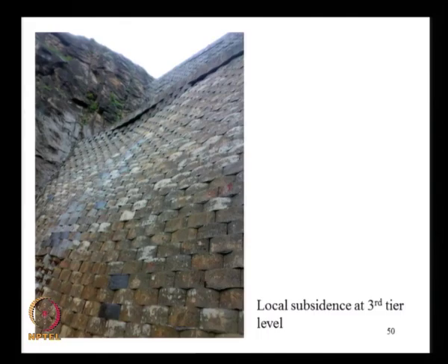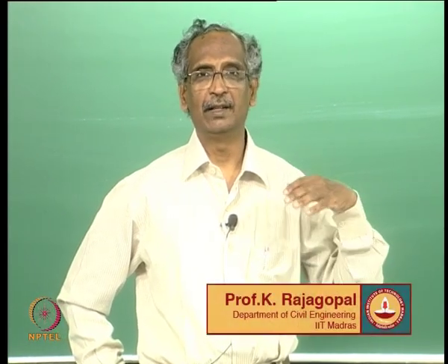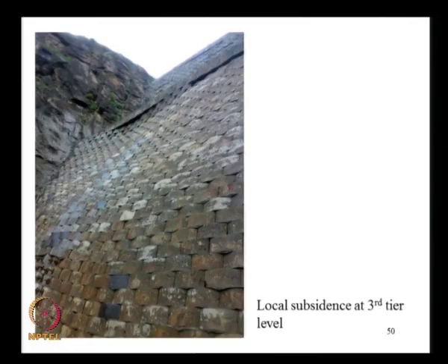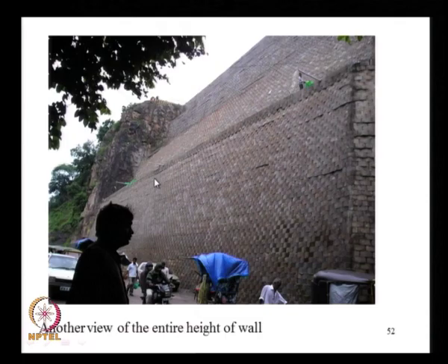And in some areas the construction proceeded during the rainy season, where there were some soft patches, and because of that there were some settlements, and you can see the effect of that local subsidence. The wall has moved inward, and there is some small bulging in one of the corners, but otherwise the entire wall is stable, and it has been there for almost 4 years without any major substantial problems.